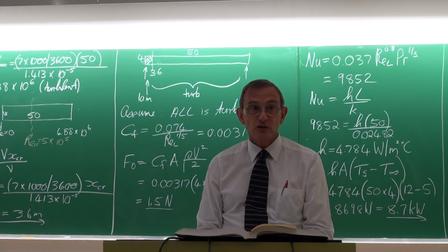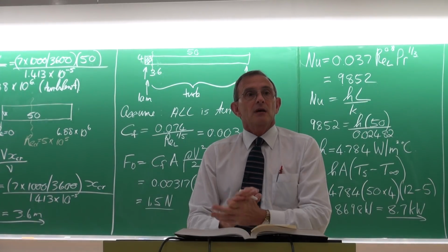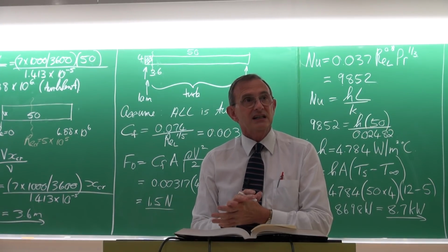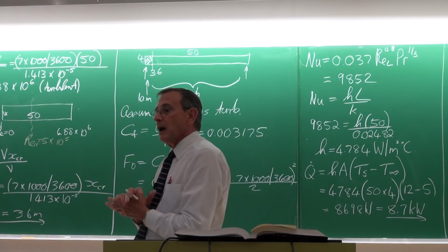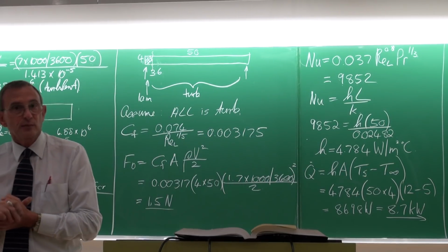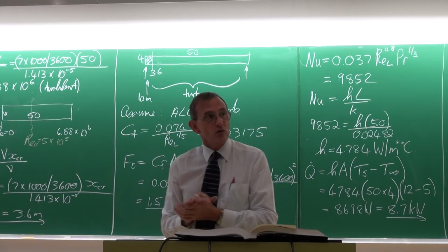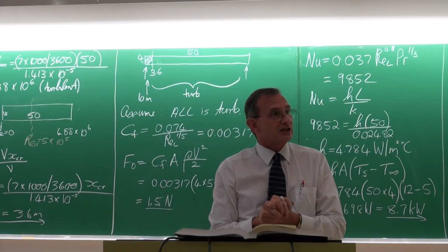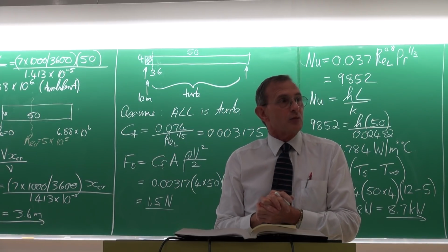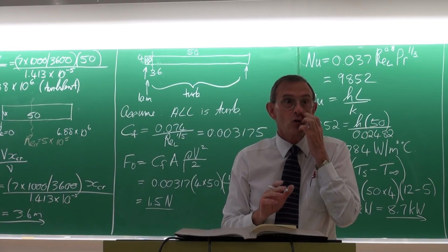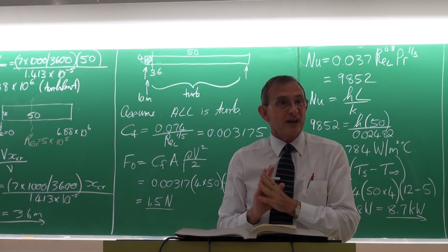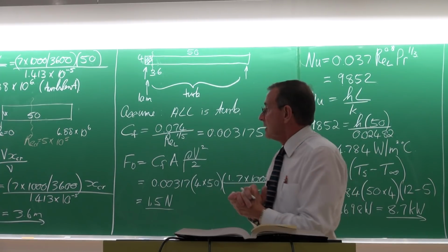They have been determined from experiments. Many of the experiments were done years and years ago when the instrumentation wasn't so accurate and when the method of determining the uncertainties was unknown. So most of the heat transfer equations are plus or minus 20%. Very, very few have accuracies of 10% or even lower.